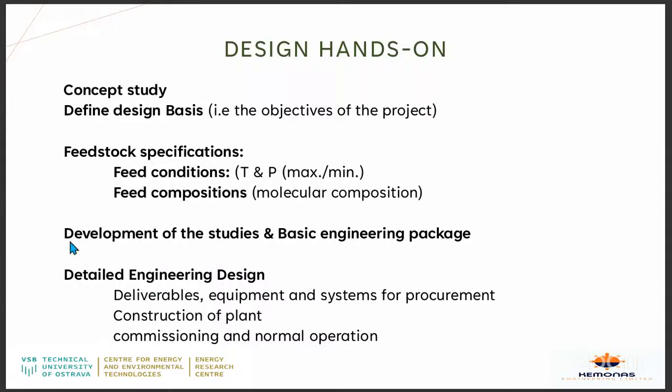So then you go into the development of the studies and the basic engineering package, where you have your BFD, then you develop your BFD into PFD, then you develop your PFD into your P and ID.